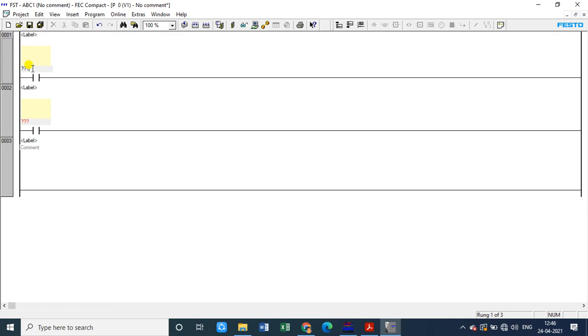Means if I want to call 1S1 here in the ladder program, then in that case I will have to insert one contact and I will have to just recall from the connections which I have made in the initial stages. That means where 1S1 is connected: 1S1 is connected to input port 1. So whenever I am considering any contact in the line and whenever I want to consider that contact as 1S1, I'll mention that as input port 1.